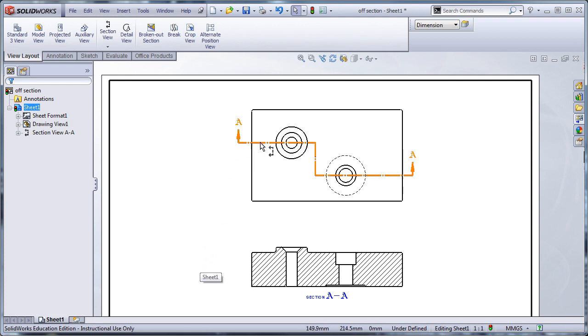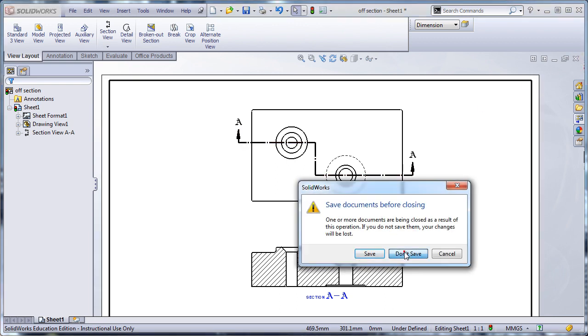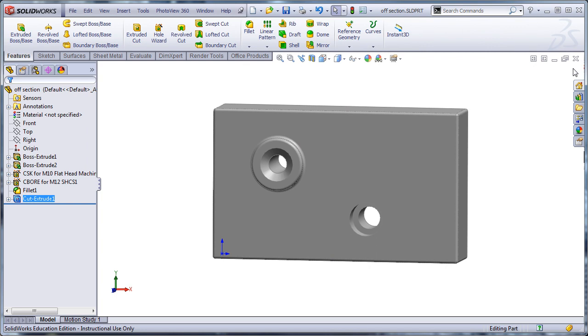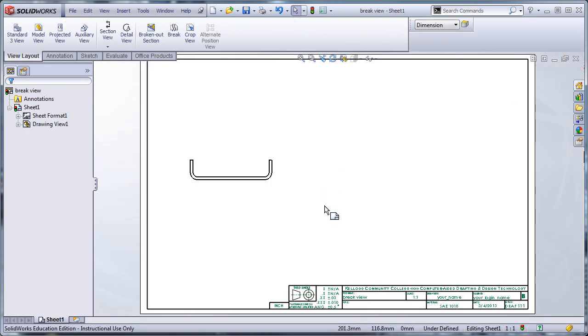Okay. So again, offset section, draw the jagged line. Make sure that you always stay horizontal and vertical. We never angle lines in an offset section, so always horizontal or vertical, and then hide that line out in that view. All right, so it's an offset section. I'm going to close this, and we don't need this any longer.